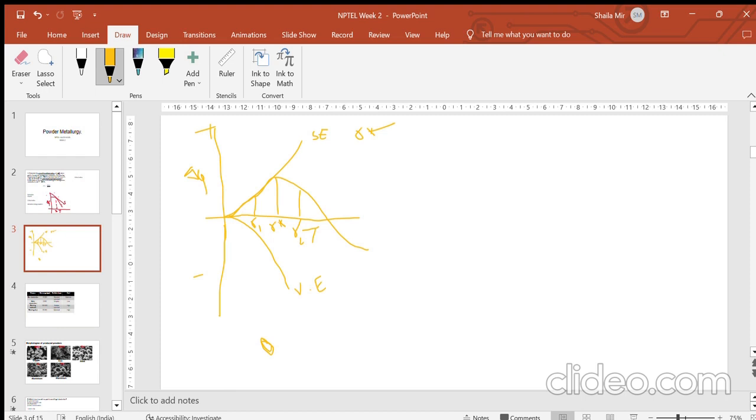Say a particle has nucleated somehow because of local heating, resulting in a particle of radius R1. But R1 is not at an equilibrium or ideal condition. So what will it try to do? It will try to decrease its Gibbs free energy. How? As a consequence, the nucleus will shrink.